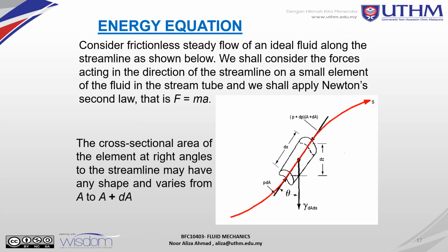Okay. So we look at the energy equation. So in chapter 3, we discuss the continuity equations, and then we discuss the energy equations. Okay, consider frictionless steady flow of an ideal fluid along the streamline, along this streamline here. Shown below, we shall consider the force acting in the direction of the streamline.